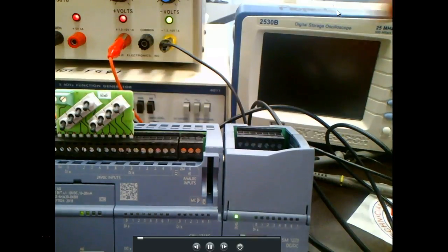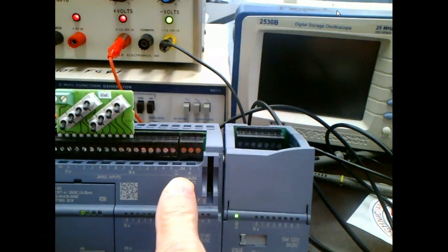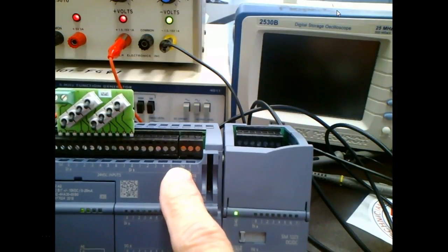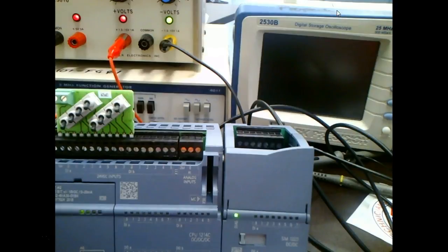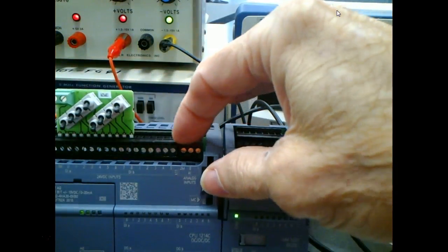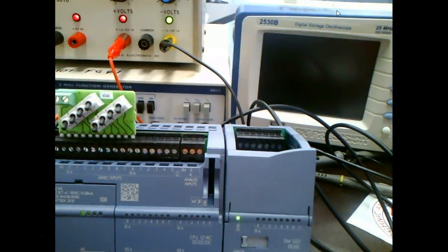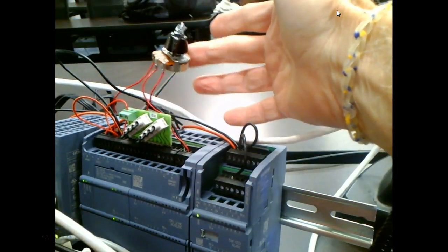Now the analog inputs are right here. Then it's got AN0 and AN1 and then 2M. So what's it looking for right here? It's looking for a common, right? Understand? So it's a sinking input. But what we can do over here, instead of putting digital values on it, is put analog values on it, so any analog sensor that's out there. Now what I have wired up, I don't know if you can see, is I'm simulating it with a potentiometer.